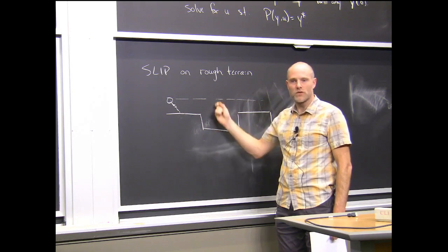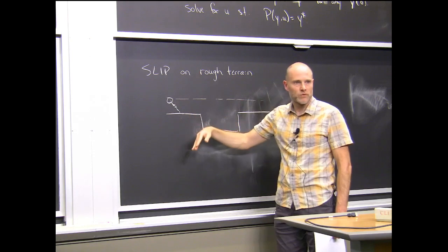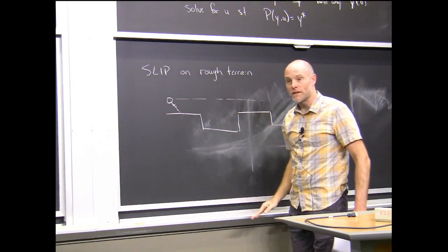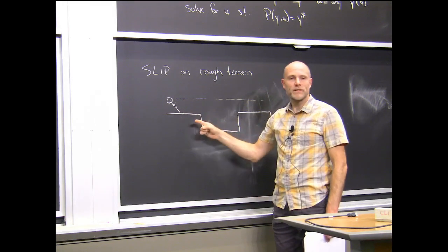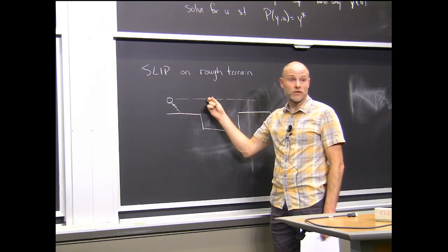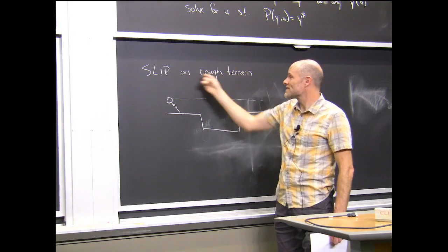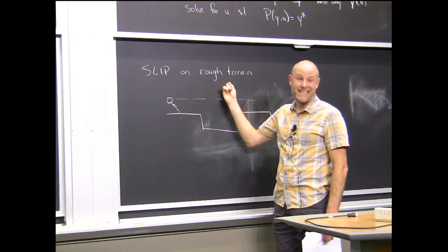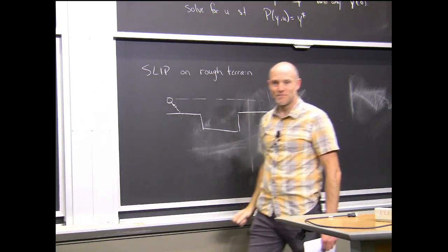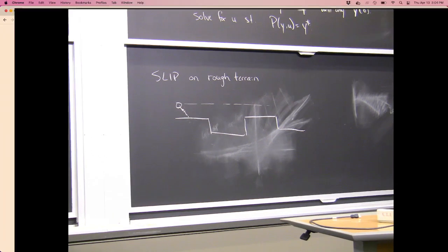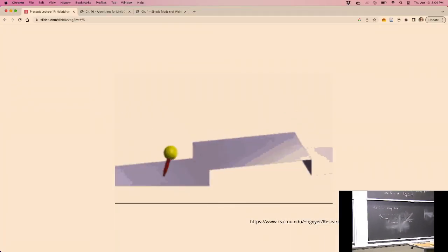Of course, up to the regime. If you go past vertical and stuff, it stops working. But in a pretty big regime, you can just close your eyes and sweep at a certain angle, and wherever you happen to hit the ground, you'll bounce back up to that in a single shot. Okay, so it's a deadbeat control for slip on rough terrain, blind, right? It's pretty cool. And Hartmut Geyer is the one who told us about that and has these nice videos of it doing exactly that.